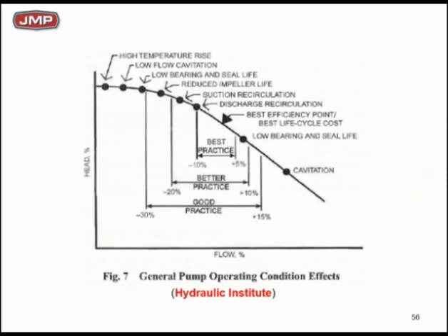So what are the pump selection guides from ASHRAE and HI? HI and ASHRAE both have some comments. Best practice, as you see from HI, which everybody belongs to, is pretty much around BEP, and they would caution you to go a little left of BEP. That's kind of what they tell you, and there are some reasons for it.